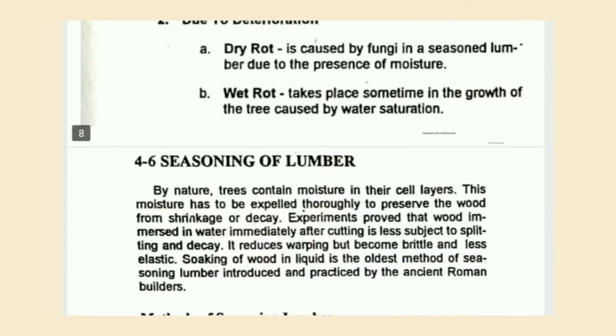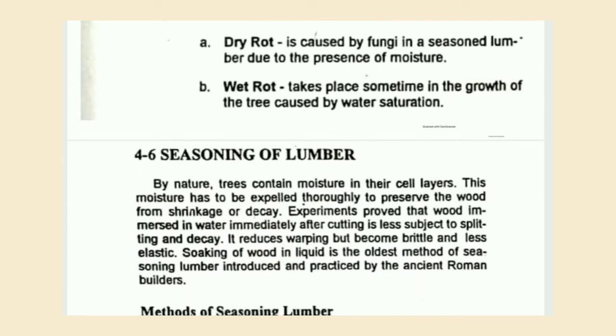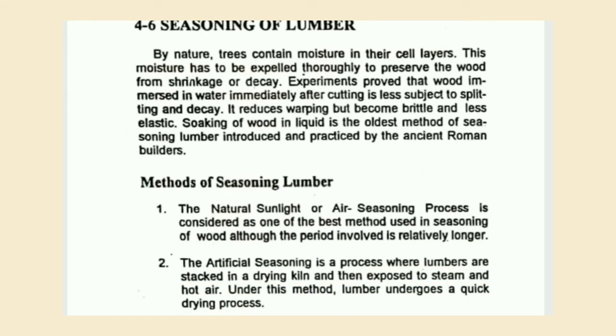So next is due to deterioration. First is the dry rot, which is caused by fungi in seasoned lumber due to the presence of moisture. Next is wet rot, which takes place sometime in the growth of the tree, caused by water saturation. Next is seasoning of lumber.